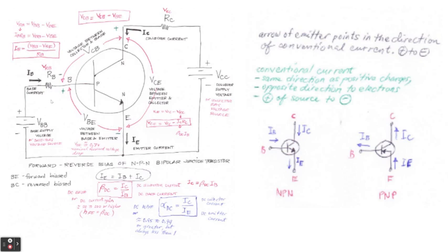In other words, the voltage VBB is equal to the sum of VRB and VBE. Now, if we want to calculate for VRB, for example, then we can subtract VBB minus VBE. And we all know that VRB can be calculated by multiplying IB by RB. So if you separate the IB, just in case you want to calculate IB, then we have VBB minus VBE over RB.